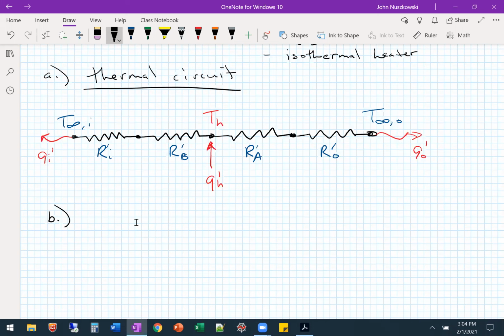We can find Q out using in minus out as our change in temperature. So which delta T are we using? The inner T infinity over outer, or minus outer? We have to follow the heat.